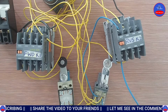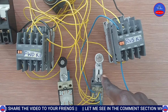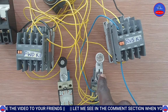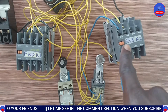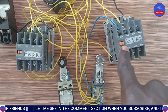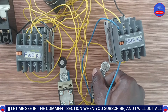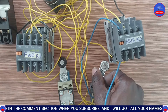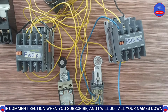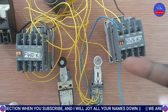Now when it gets to where limit switch 2 is placed, we are going to trigger it. Let's see, and also see contactor 2. See that K1 is off, and then K2 is now on. So now it has reversed its direction. Now it is coming this way.